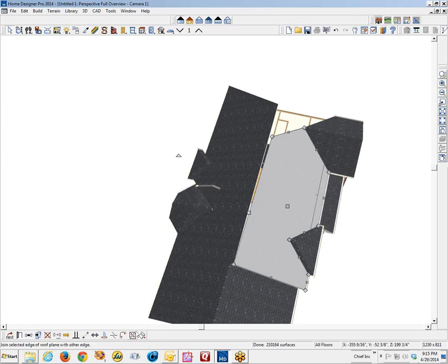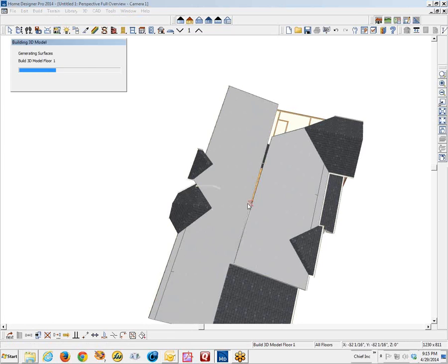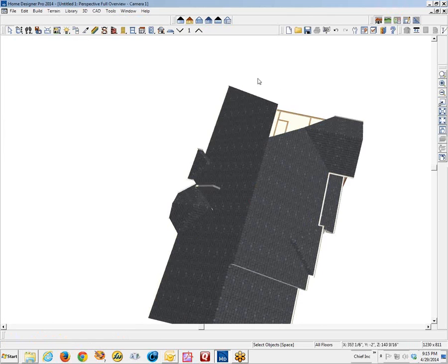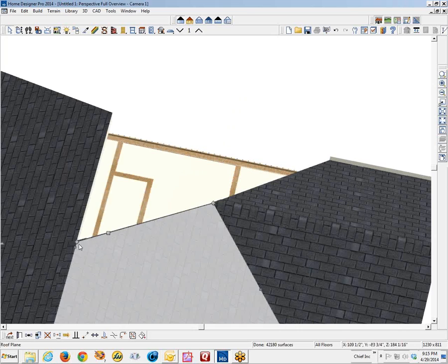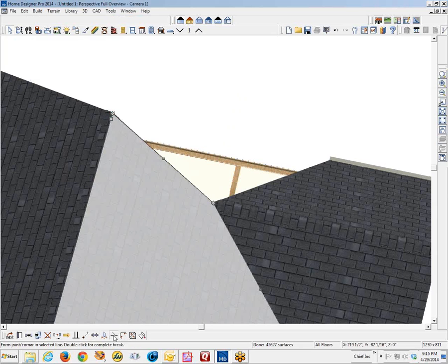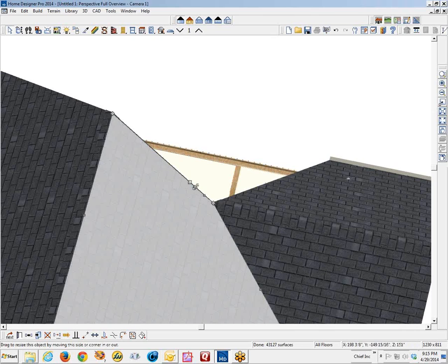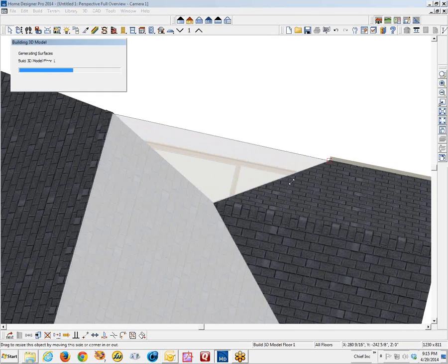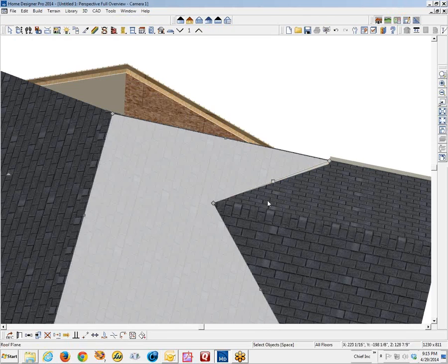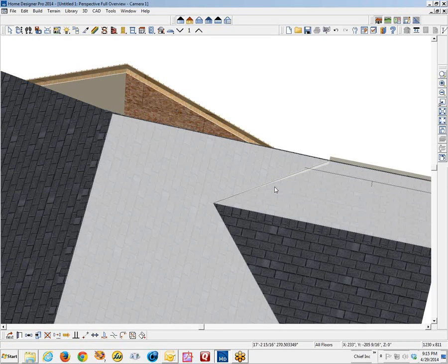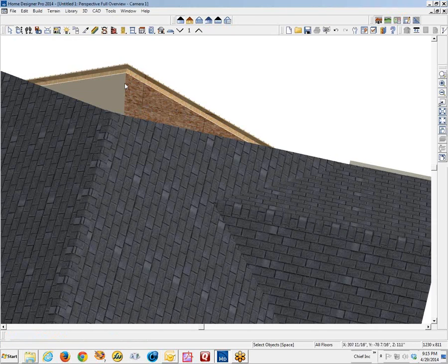Now this main ridge, I'm going to do it next. Let's join the main ridge, and it joined because I did all the preliminary setup already. This end here, I'm going to extend it out over there, add a break around this gable roof here. Let's get it kind of close, then join roofs there. That's popping up because this is most likely not overhanging properly.